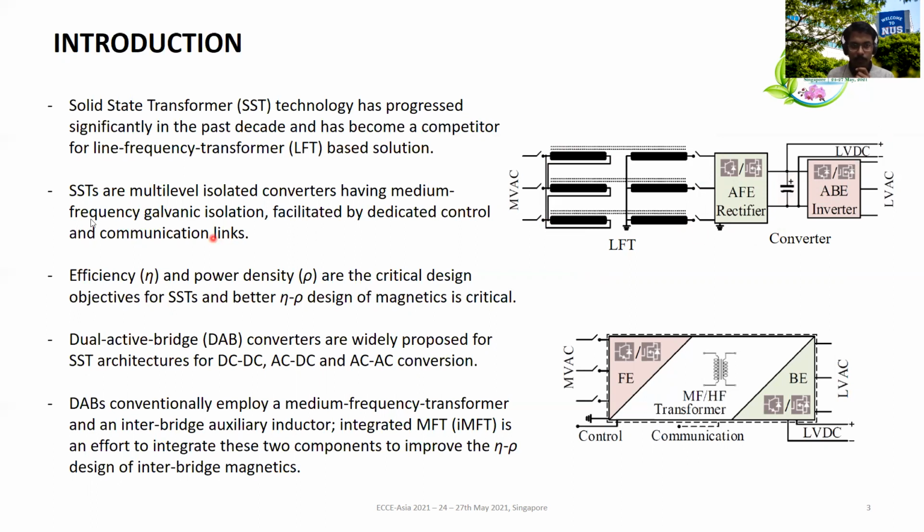Now, solid state transformers are multi-level isolated converters having medium frequency galvanic isolation, as you can see here, with a front end bunch of power electronics and a back end bunch of power electronics with medium frequency isolation. Here is where the medium frequency transformer comes in, and this SST is facilitated by dedicated control and communication links.